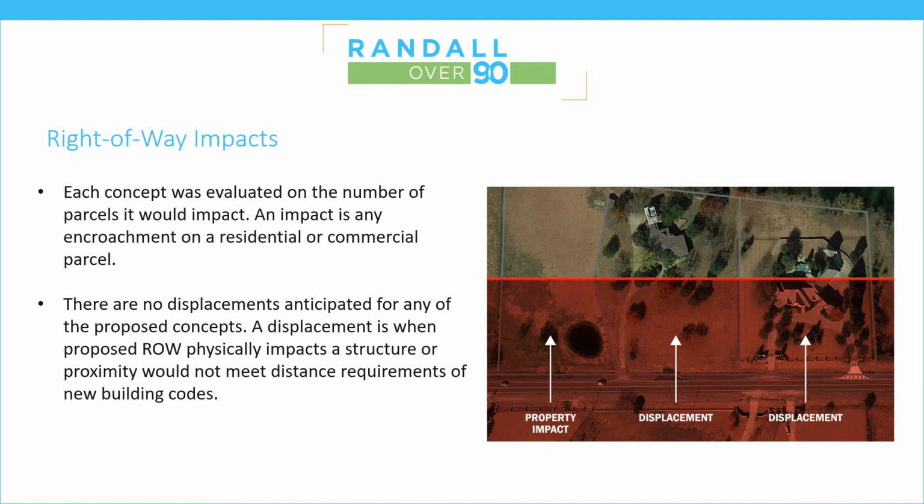Right-of-way. Each improvement concept was evaluated and scored based on the number of parcels it would impact. An impact is any encroachment on a property. Any concept that requires many impacts to parcels scored lower than those that had few or none. It is important to note that there are no displacements anticipated for any of the proposed concepts. A displacement is when proposed right-of-way physically impacts a structure, or proximity would not meet distance requirements of new building codes, requiring the purchase and removal of that structure.